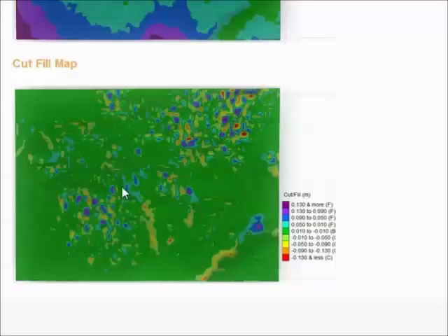You can see here there's a couple of drainage flow paths that have been calculated by the software. It's filled an area in here and cut an area there to get our minimum grade also here. Now the software does that automatically. It works out the best way to do the earthworks to minimize the earthworks.